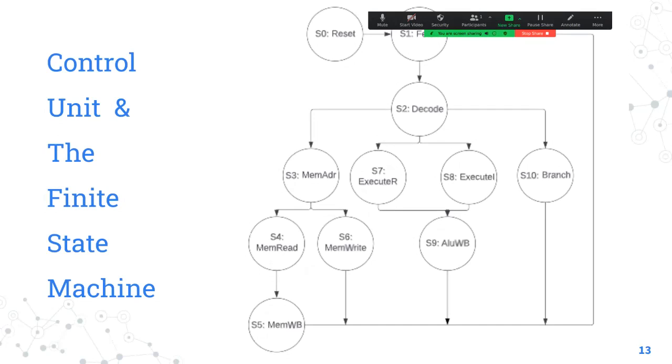When you do an operation, it takes some time for the final registers or the wires to settle to the correct value. Let me tell you an experience. Once we decided the clock, we kept the clock at a very large time period. The clock is very slow. It would take, I think, 1 second for one instruction to execute. We made that for debugging purposes, to just monitor each stage, and we kept reducing the time period. We kept increasing the frequency to see whether the final thing would actually work.